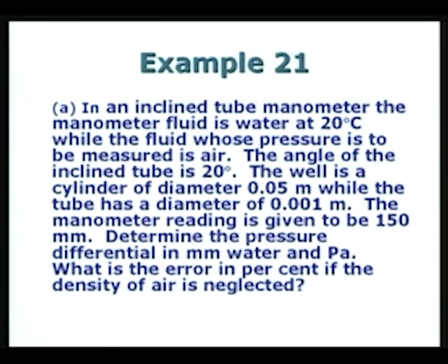We also would like to find out what is the error in percent if the density of air is neglected, because if you remember in the last lecture we talked about the fact that the density of the manometric fluid and the density of the fluid in which the pressure is being measured, both are going to play a role, and in many applications we could in fact neglect the density of the fluid in which the pressure is measured.